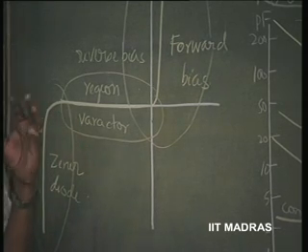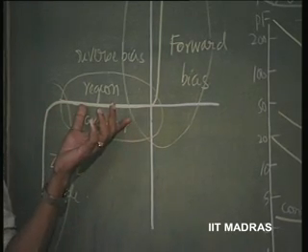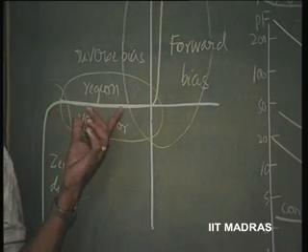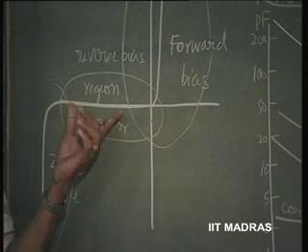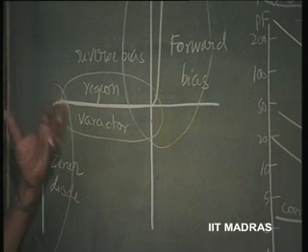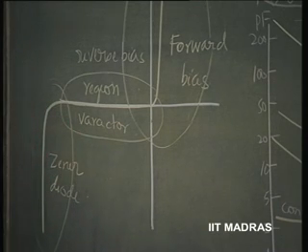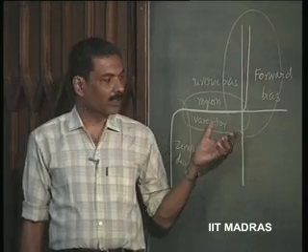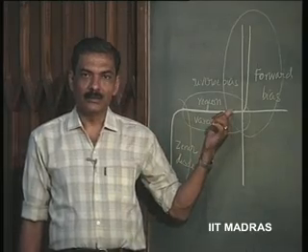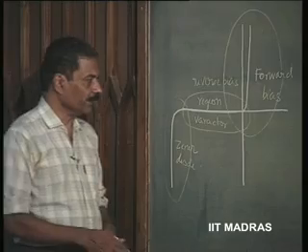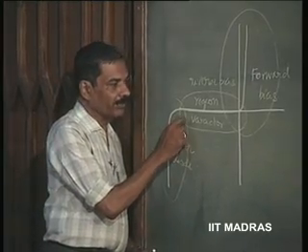But therefore, you have to remember that power diodes sometimes should not be really used for high speed applications, because the capacitance of it is really very high. So, that means for high frequency rectification, you should not use conventional power diodes which are used for 50 hertz. This is the normal confusion that exists. For rectifying a high frequency waveform, we must never use a power diode, because it is going to still conduct because of the capacitance. Therefore, this kind of thing we should be very careful about.